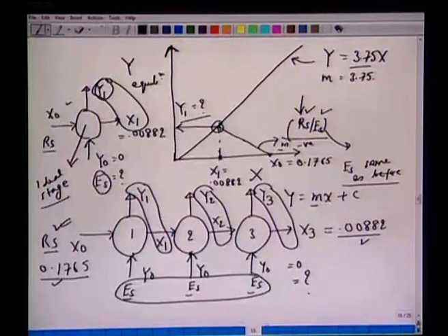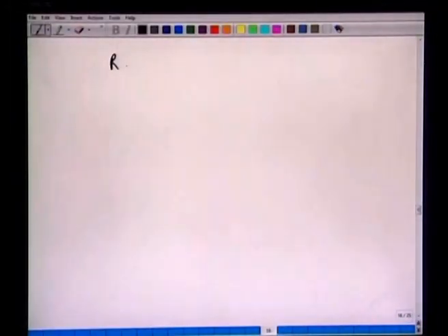One can write down the material balance or species balance for all 3 stages. Okay, so let's write down the same balance which we wrote, right? So what enters from the first stage is Rs, Rs (x0 minus x1). This will be same as if we write down the second equation which we had for the second stream, which is Es (y1 minus y0). So that's stage 1.